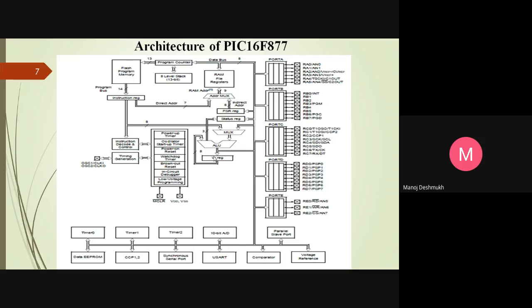But here the working register plays a similar role, with an additional facility: if you want to store the result somewhere other than the W register, it is also possible by specifying the bit status after the instruction, that is comma 0, comma 1, like this. We will see later, but keep in mind that W is exactly similar to the function provided by the accumulator in 8051. It does not mean the result is always stored in the W register.